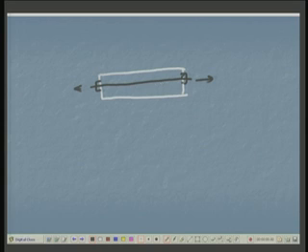When I anchor it up here, what will happen? Since I have already pulled it and given some strain to it, within the elastic range, it will try to shorten, because I have put some stress onto it. When it tries to shorten, it applies a compressive force onto the concrete.